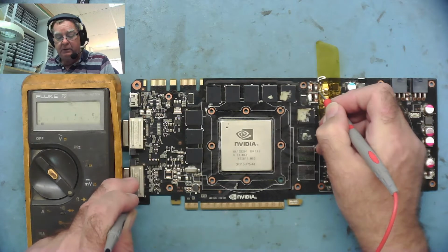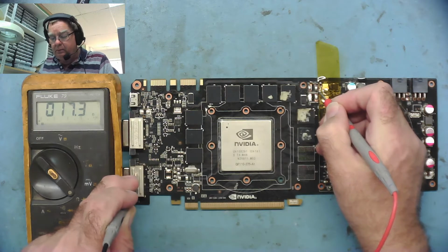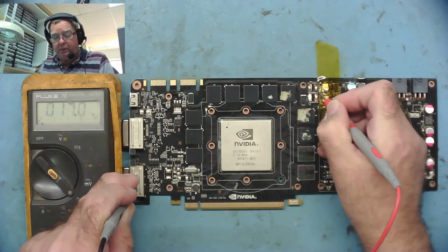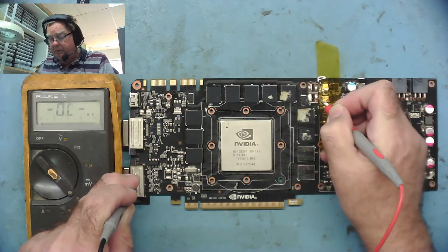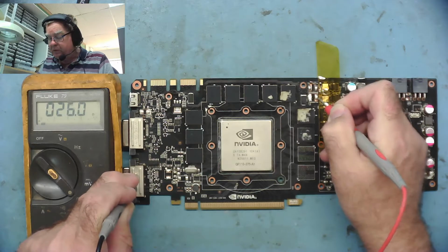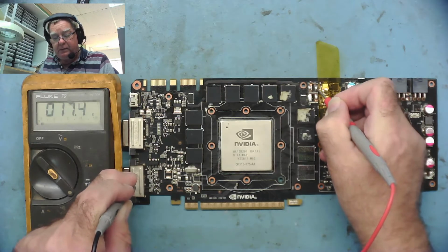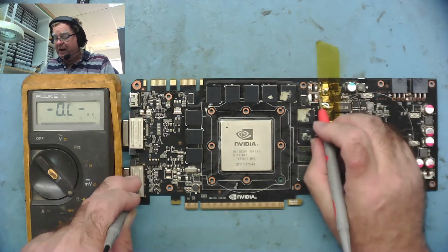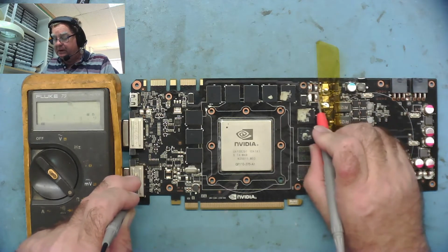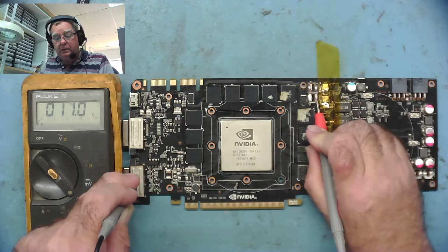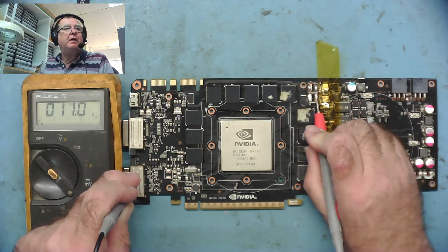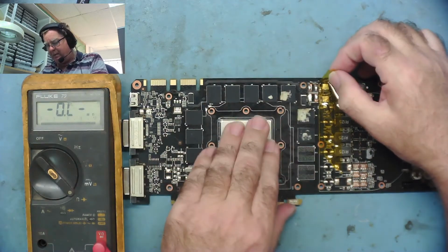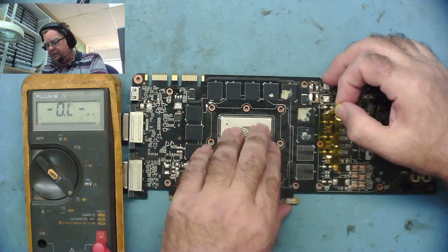What's on this side? Yeah, low. This one is a bit lower than the other one, because they get into the different phases. So that's where the low resistance is. Obviously these were in parallel before, so I'll see if I might be able to get across the two of them. Yeah, which now across both of them is 11 ohms. So there's our low resistance. It's not the RAM. It's not the GPU.